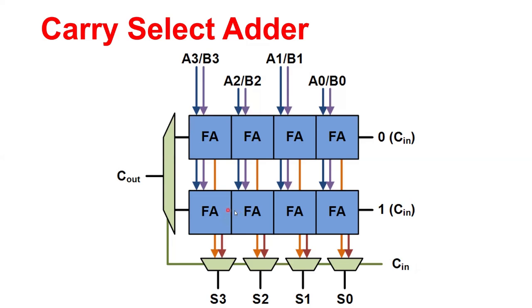Of course, it then means the carry is rippling from this stage, because at this stage the carry got generated. So the carry gets propagated from this stage to the final stage, that is the MSB. So there is this delay right over here, and then accordingly the brown sum line gets connected to S3, for example, right over here.